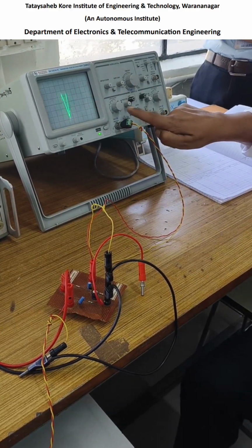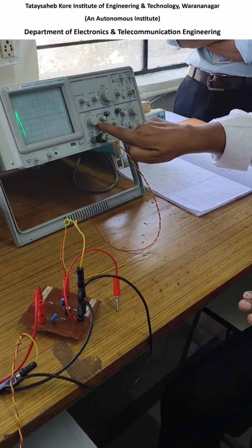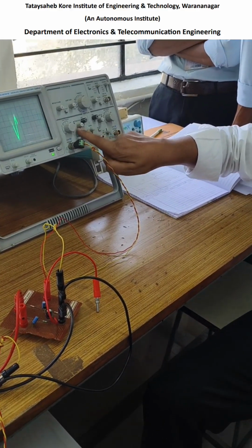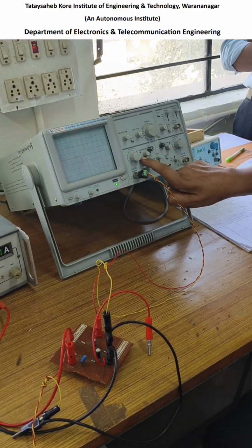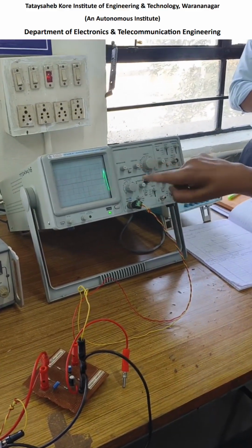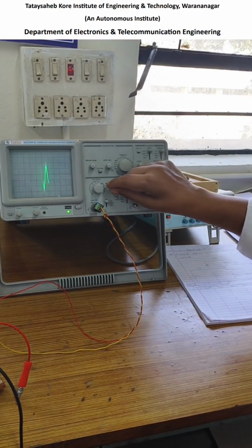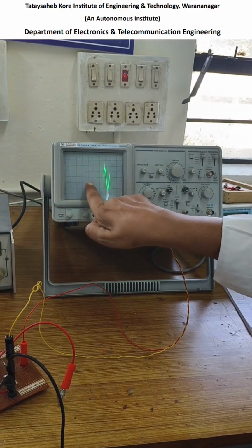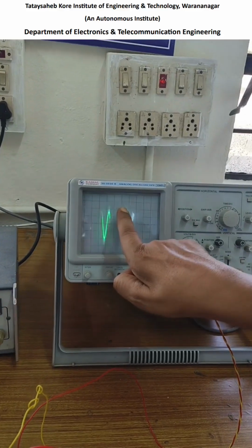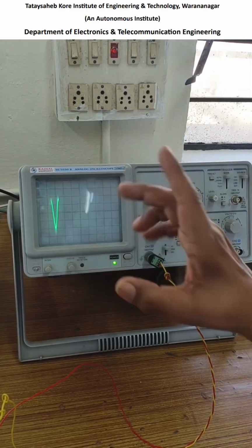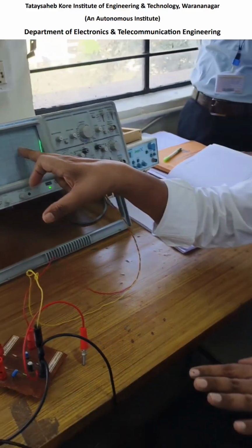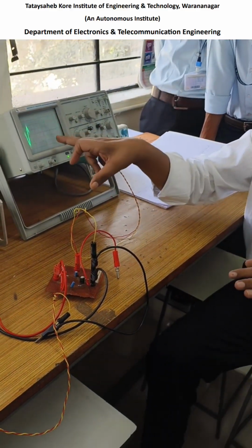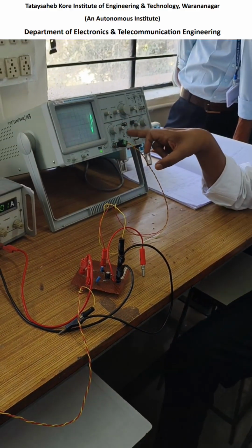Now carefully see, this volts per division is on 20. So what is my multiplier value? 20 millivolt. This 20 means it is millivolt. Carefully remember this. Now, if I check using this Y position, how many lines are there for my output signal? Carefully check. 1, 2, 3. And it is not exactly 4. I can say it is 3.8. You have to take the approximate value. So it is 3.8. So using calculator, you just find out 3.8 into 20 millivolt.